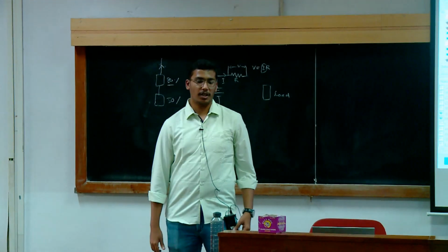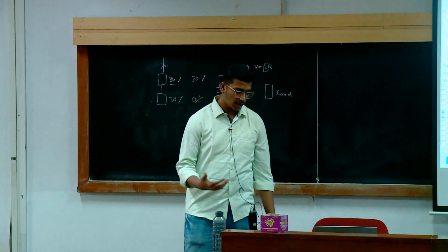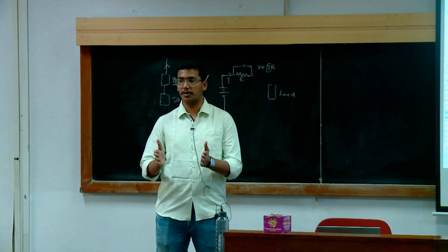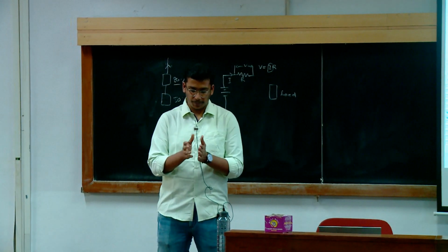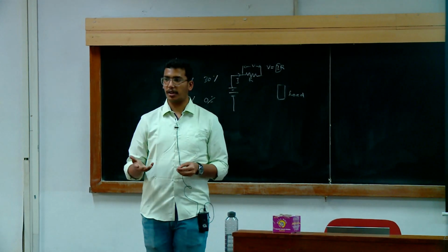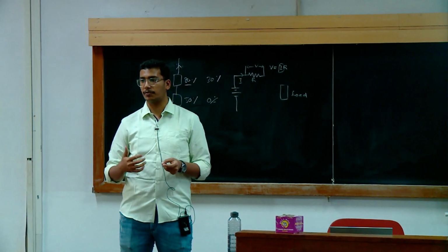Because as you mentioned, if a cell nominally charges in 5 hours, and we want to fast charge it in 1 hour, then definitely we have to pump in more current, and that does not give enough time for the balancing algorithm.